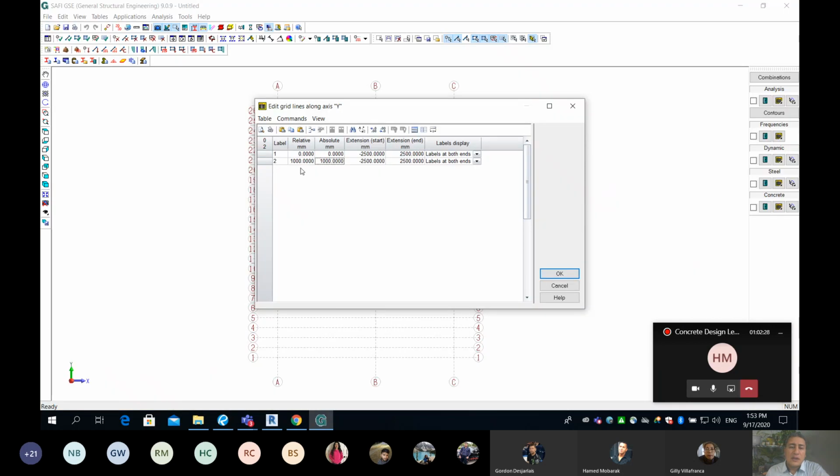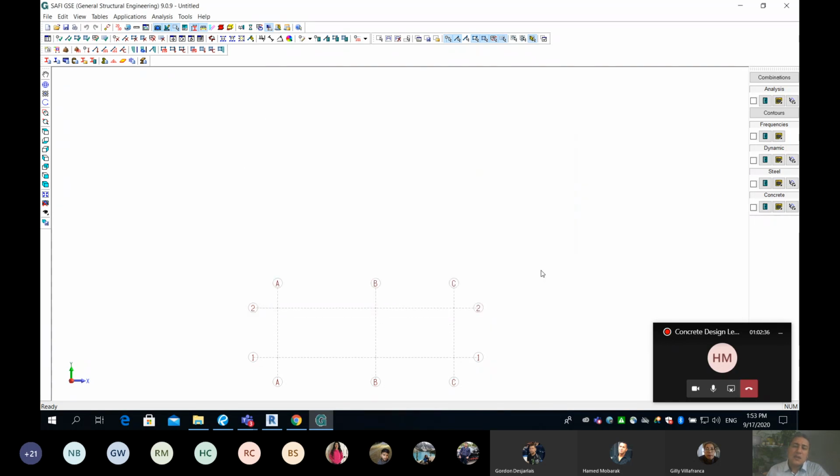And that's where I come here. I go to this number here, and I type in here 5,000. Okay. And then accepted and hit OK. Another OK. Congratulations. Please watch this. Now, the thing that really annoys me with this software: if you try to use the mouse the same way you use it in AutoCAD, it just changes the rotation of your view. So if you want to pan things, that's what you have to do. You click on the handle on the left side here. You click on the handle, and simply you translate, and you scroll your mouse. Then you can see I'm zooming in.